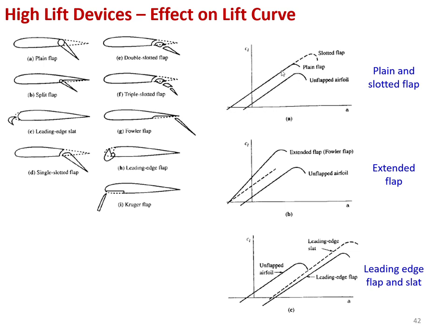If you make it a slotted flap, this is going to encourage the flow reattachment, because some streamlines from the lower surface are pushed to the upper surface and cause reattachment or reduce the adverse pressure gradient.